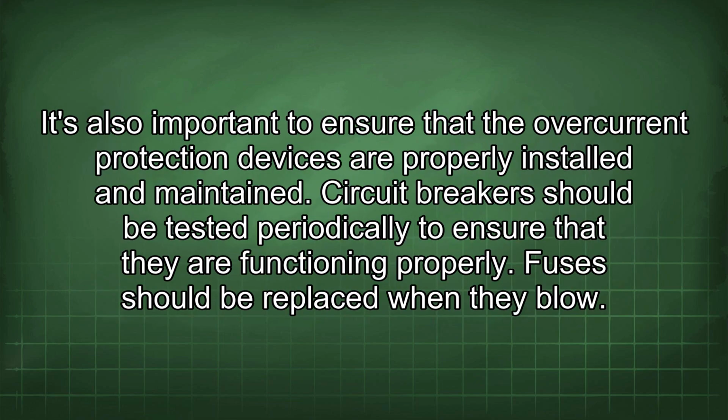It's also important to ensure that the overcurrent protection devices are properly installed and maintained. Circuit breakers should be tested periodically to ensure that they are functioning properly. Fuses should be replaced when they blow.